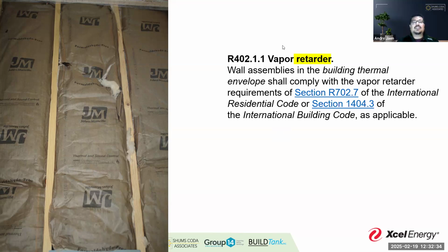But for the folks that joined us a little bit late, we're talking about these puzzle pieces and the way they're presented in the core code in sort of an idyllic form. I'd strongly recommend, if you've been running into circumstances where you're getting some really complex assemblies in the high country, you're worried about vapor locking roofs or wall systems, you're getting more exterior insulation being mixed with more stringent class 1 vapor retarding systems, and whether or not that's at all possible, again, I'd point you back to a couple of those Joe Straube articles.